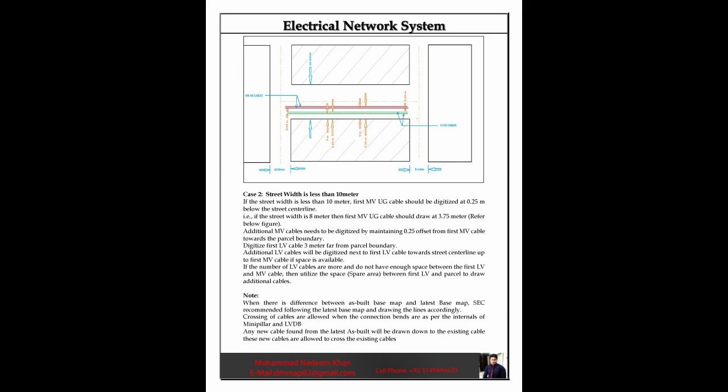if space is available. If the number of LV cables is more and there is not enough space between the first LV and MV cable, then utilize the spare area between the first LV cable and the parcel to draw additional cables. Note: when there is a difference between the as-built base map and the latest base map, SEC recommends following the latest base map and drawing the lines accordingly.